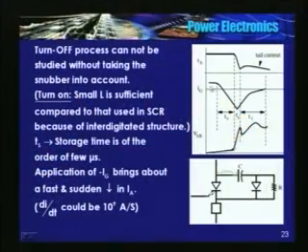See in this figure, at steady state, we had reduced the gate current to a very low value. Somewhere at this point, you decide to turn off the GTO. So Ig reverses. Though Ig has reversed, IA still remains constant for Ts duration.